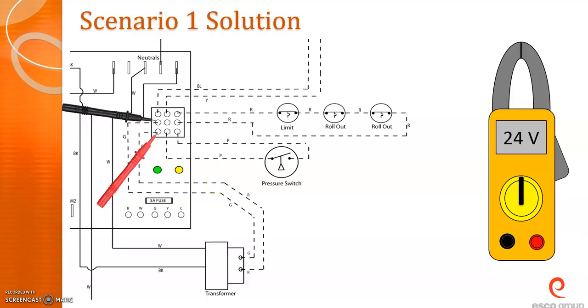If you have 24 volts present, then obviously you have high voltage coming to the transformer, so you don't really need to check the high voltage at that point. If you didn't, then that might be a good time to go back and check the high voltage just to make sure. Obviously, your door switch can also come into play. If you have the door off, you have to have that door switch pushed in to actually get the call, so don't forget that.